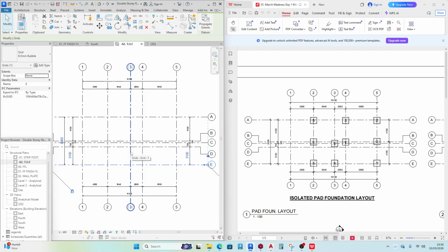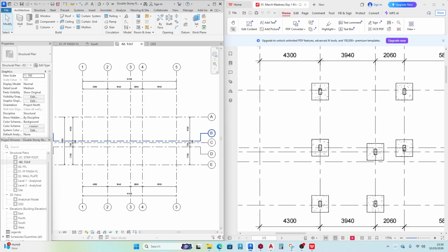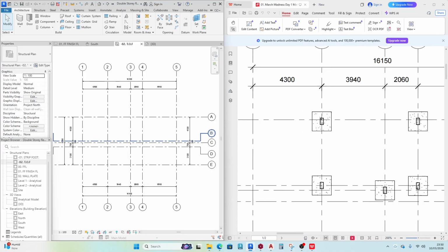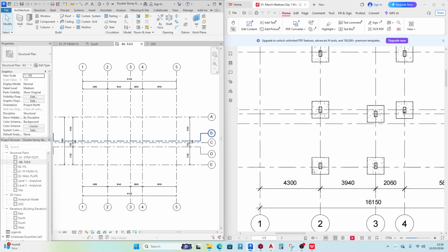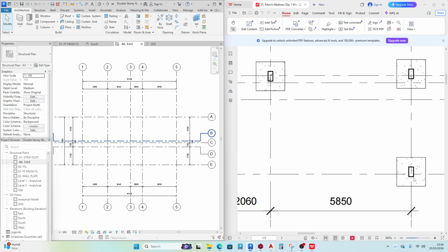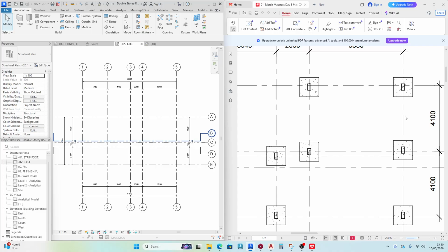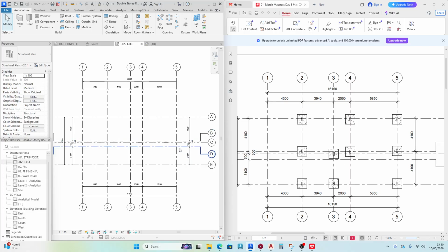We'll assume we're going to use 200 by 400 structural columns. And then, are they going to be centric or not? Let's zoom in. Yes. Here it shows we will have about 100, I guess, for the wall. But these other ones are going to sit perfectly. The bottom ones also will be a little eccentric. Also this one. So you can place columns individually.